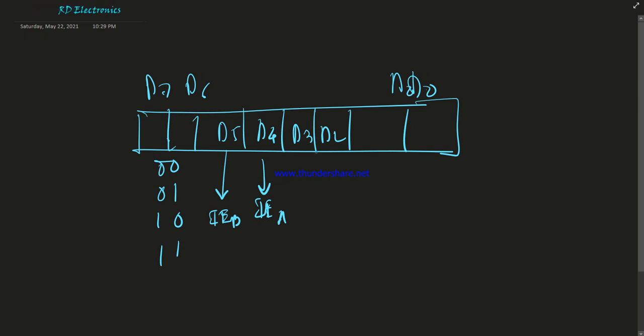D3 and D2 are used for port C. When 00, it is ALT 1, the assignment of the defined purpose of port C. When 11, it is ALT 2. When 01, it is configured as ALT 3, and 10 is ALT 4.